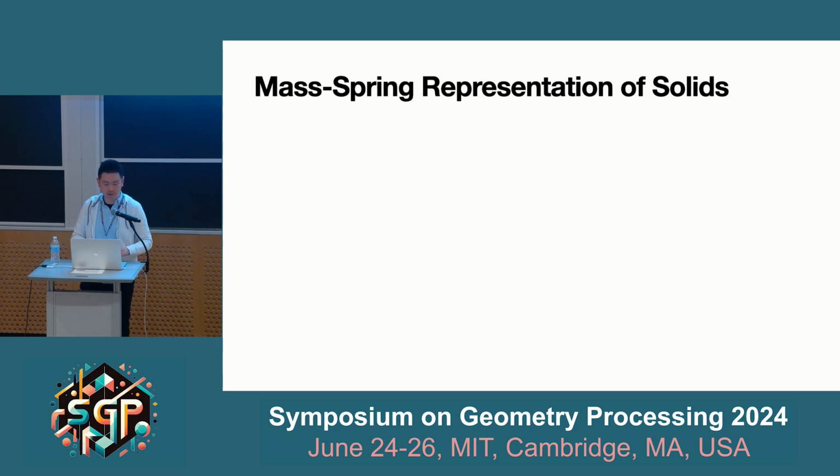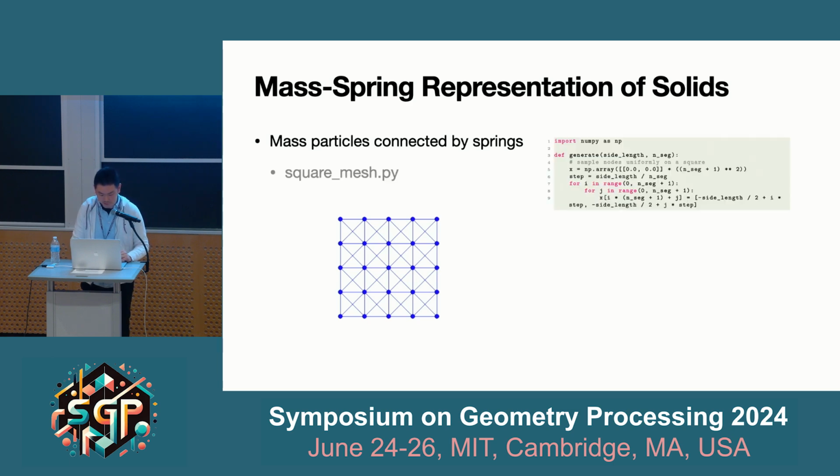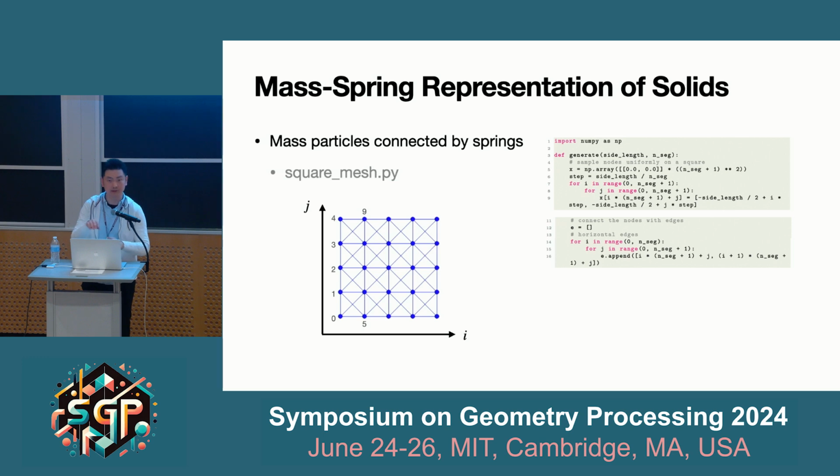So here we are introducing another slightly different but easier model for modeling the elasticity of solids using springs per pair of points. So here we first create a square, or say a matrix of points, and then use edges to connect them per row, per column, and also per diagonal. And here, each edge will be represented as a spring, which if you stretch it, will exert forces to drive the length to the original length.